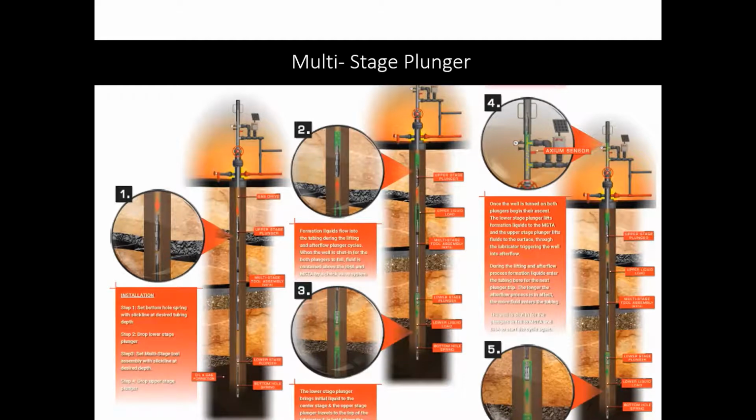There's a plunger that runs from the end of tubing, the BHA, to the stage tool. There's another plunger that runs from the stage tool to the surface. The multi-stage tool has a standing valve to retain fluid above the tool during shut-in. These are designed to partition the well's fluid and load per cycle, and reduce shut-in time in comparison to a single stage well that requires pressure build, because the plunger travels half the distance. So it reduces extended shut-in time for casing buildup.